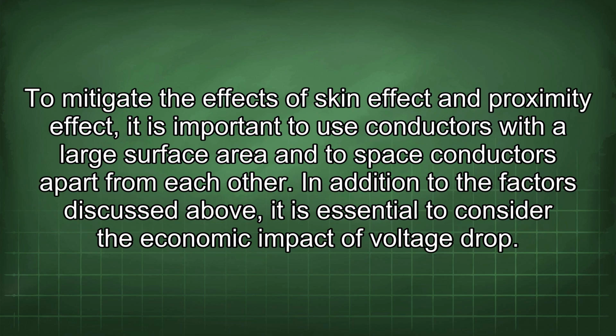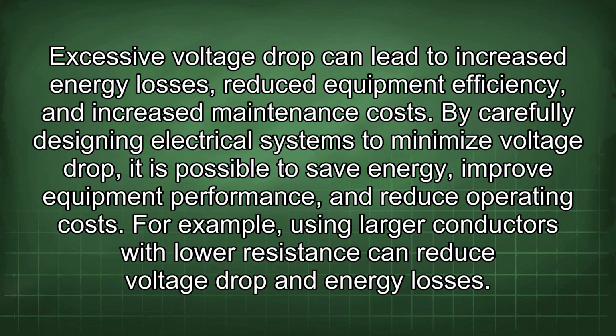To mitigate the effects of skin effect and proximity effect, it is important to use conductors with a large surface area and to space conductors apart from each other. In addition to the factors discussed above, it is essential to consider the economic impact of voltage drop. Excessive voltage drop can lead to increased energy losses, reduced equipment efficiency, and increased maintenance costs.